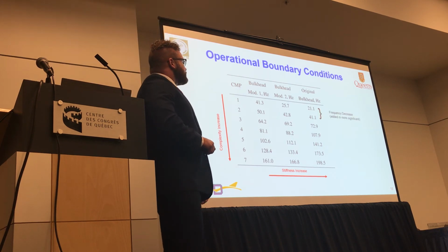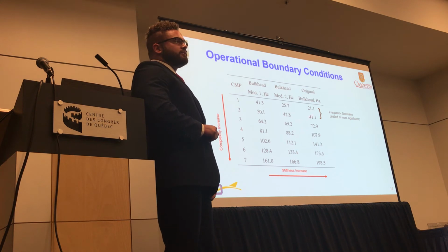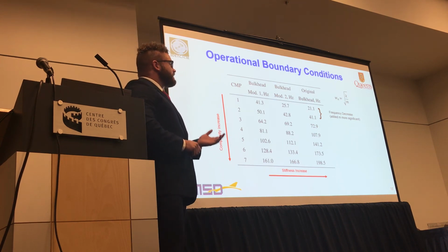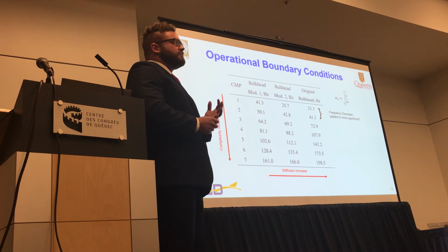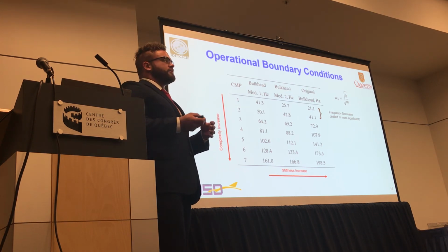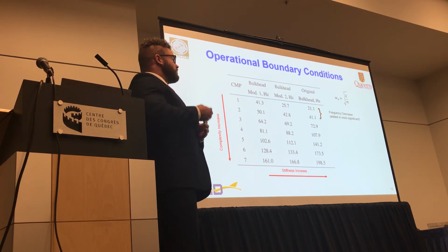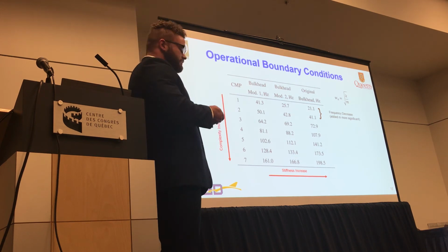So the key results that we found were that the first two modes actually decreased in natural frequency, which means, if we remember our definition of natural frequency, that the added mass had a greater effect than the added stiffness. I believe this is due to the displacement of these mode shapes in particular, because we see very global modes, where the mass inertial effect would be a lot more significant.